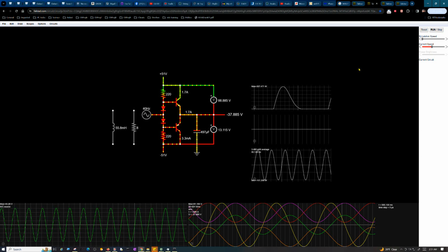You only see warnings about inductive loads, but capacitive loads of similar magnitude would be equally problematic. It's just like in a lamp dimmer, you only see that warning because they don't expect you to have a big capacitor hooked to the light socket up there. But you might have a ceiling fan, so that's where that comes from. That's why sometimes they talk about one and not the other. But really, it's reactive loads in general that are a problem with overheating transistors.